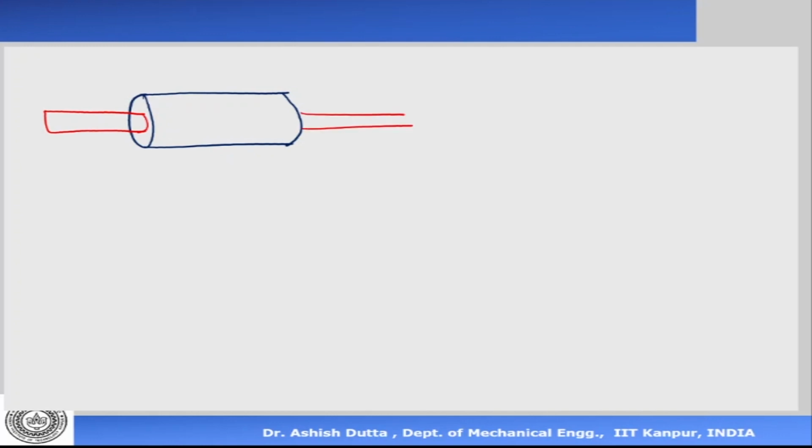And this link can move front and back. So that's my link number 2. And there is link number 3, which is connected here to the end effector. Okay, and let me say this can rotate about this axis. Now this contains a revolute joint. Which is the revolute joint? If you can imagine, it can rotate about this axis. So that's a revolute joint. Okay, that's a vertical axis.